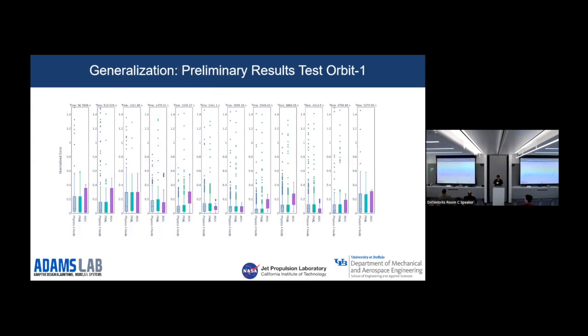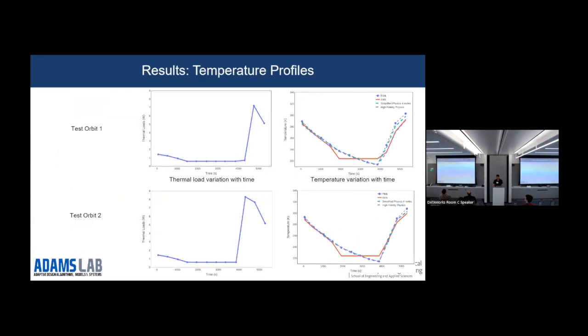However, the reasons why we don't just do data-driven modeling, right? This was a small dummy example, and in a very small simulation, you might get results like this, but there's still some downsides because the ANN, as in the purely data-driven technique, cannot extrapolate. For instance, if I've given it thermal loads for a specific orbit, it might not be able to tell me the performance for an orbit which has loads that it hasn't seen before, right?